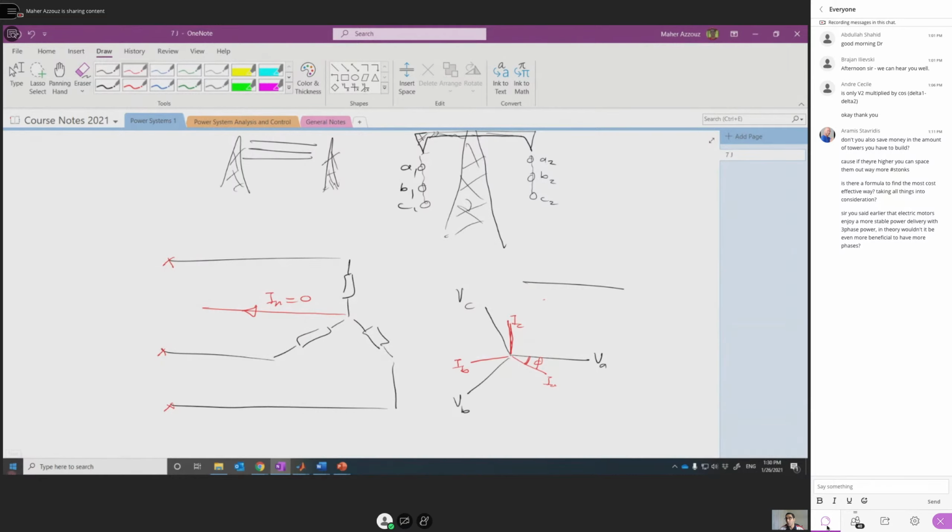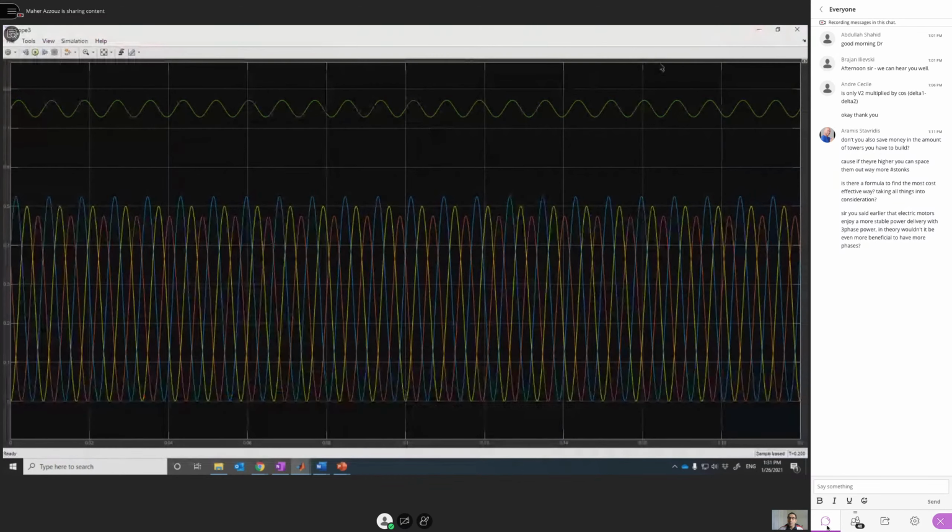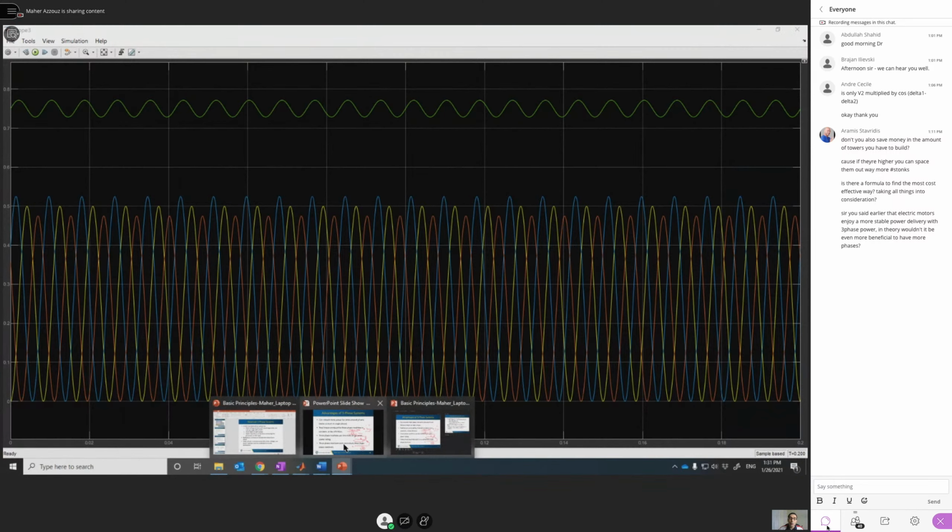But when we approach distribution systems, I mean, when the transmission line is near the customers, the cities, the distribution utilities, then we need to have the neutral wire, because loads are not balanced. Loads are not exactly identical. Utilities and power system operators try to balance loads, but at the end of the day, there is an amount of imbalance. And as I told you, a small variation in the voltage magnitude will create oscillations in the active power. So we need to have the neutral wire.